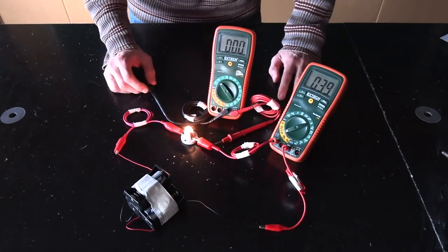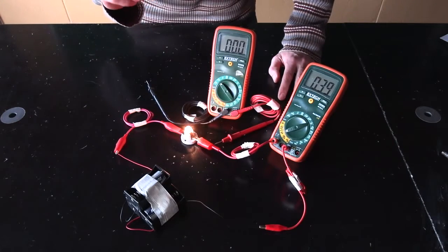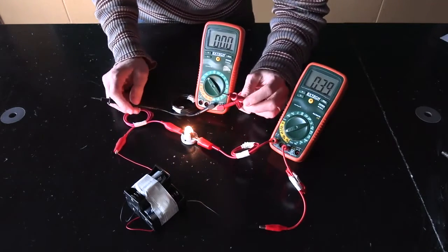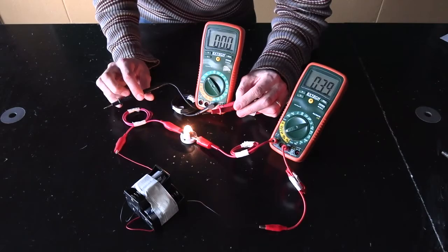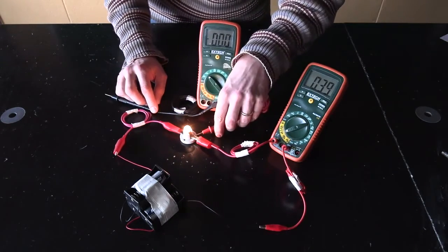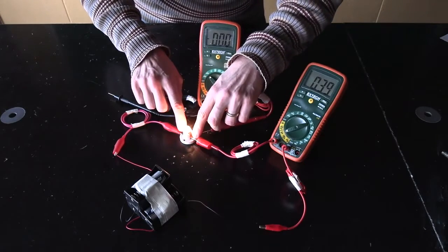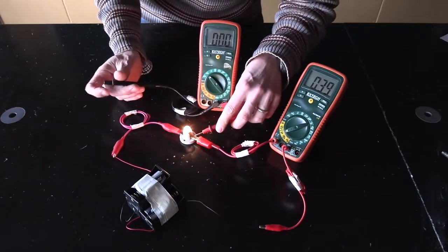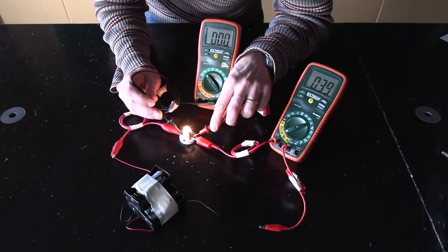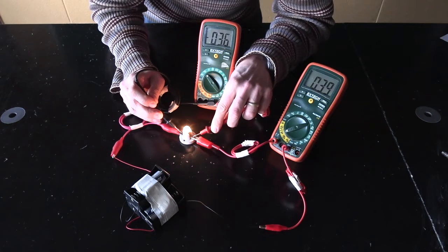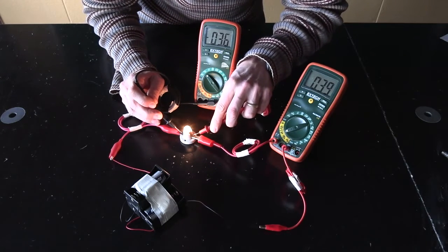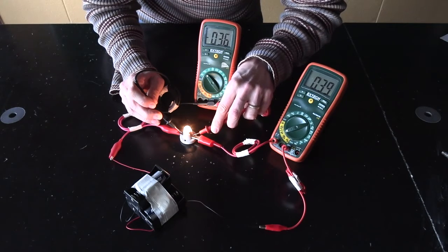So again, remember, voltage is always between 2 points. So now when I take these voltmeter probes, if I want the voltage of the light bulb, what I need to do is measure, not like this, but from one side of the bulb to the other. And that means touching this here and the other wire on the other side of the bulb, and you see that you get a reading, looks like about 3.6 volts of the light bulb.